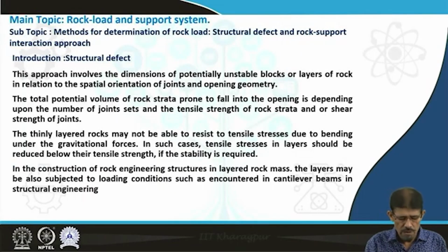Friends, as you know, the structural defect approach, as the name indicates, involves the determination of potentially unstable blocks or layers of rocks in relation to the spatial orientation of joints and opening geometry.